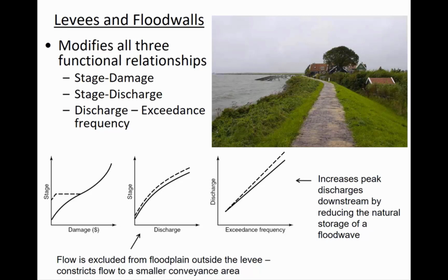because you're kind of forcing more of the flow to be in contact with less of the wetted perimeter, and so you're increasing the flow capacity of the stream. And so for a certain flow rate, the discharge could be higher. For a certain size storm, the discharge is going to be higher. It increases the speed of the water's travel, and so it's all concentrating a lot more fast.